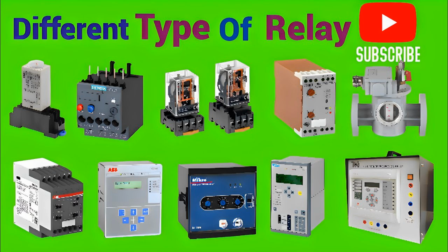Ground fault protection. Relays are utilized for ground fault protection, which safeguards against electrical faults that occur when current flows from a live conductor to ground due to insulation breakdown or equipment malfunction. Ground fault relays detect the imbalance in current between the supply and return conductors and trip the circuit or activate ground fault interrupters, GFIs, to disconnect power and mitigate the hazard.